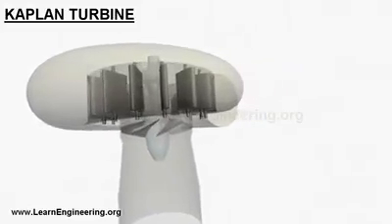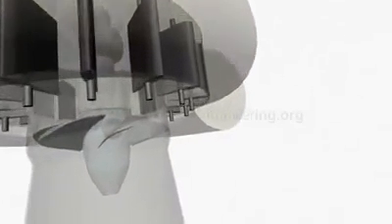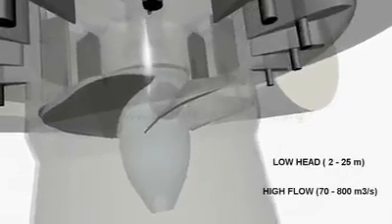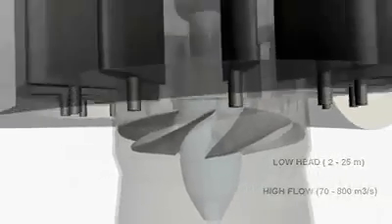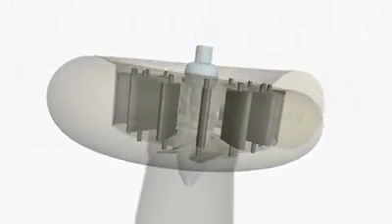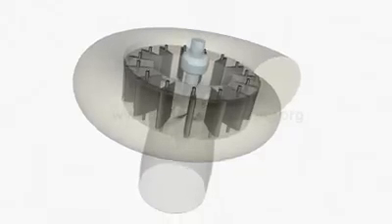Kaplan turbines are suitable for power extraction, when water energy is available at low head and high flow rate. Which means, they are suitable for operation when water is stored in a big reservoir, at a relatively shallow altitude.